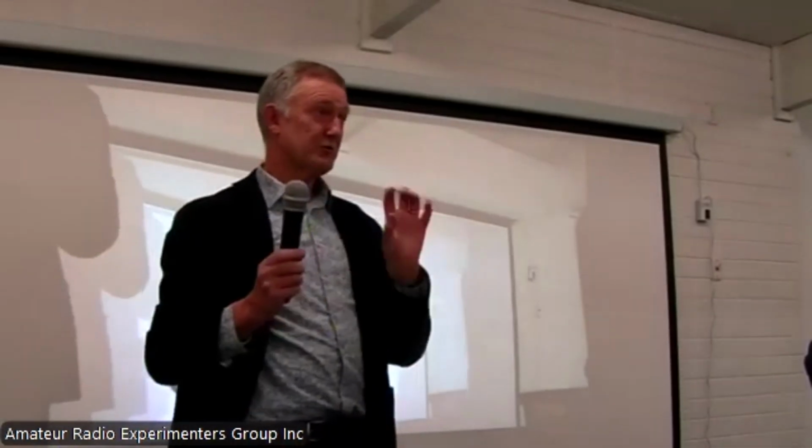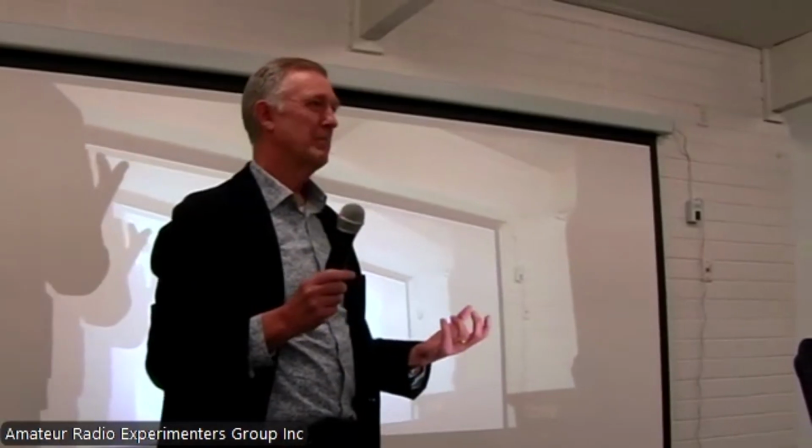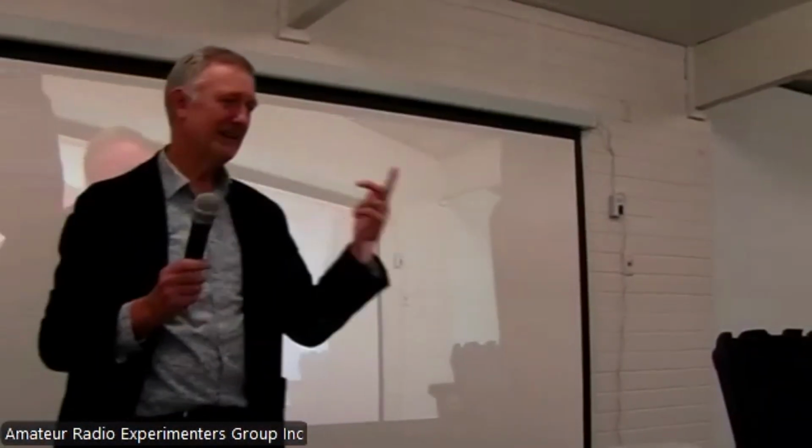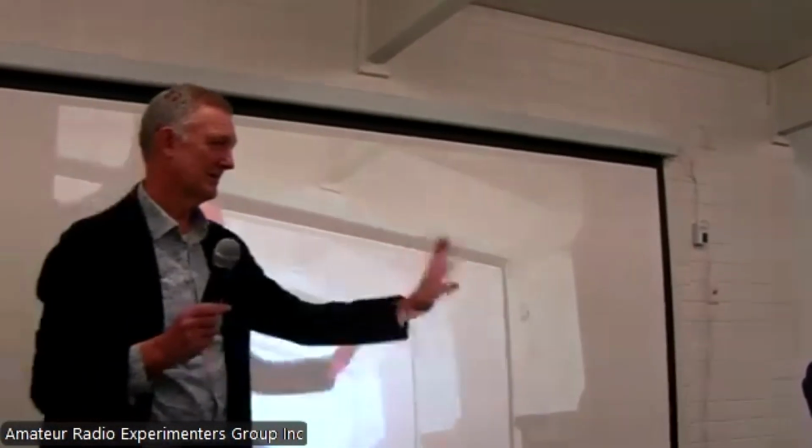The 63 is the junior brother. The 61 is the senior. The 63 is converted into a 61 by a software hack. It doesn't do the same type of bandwidth. It doesn't do the same type of minimum frequency, but it does things very well and costs a fraction of the price. So it is one of the most popular chips out there that's in the software-defined radios today.